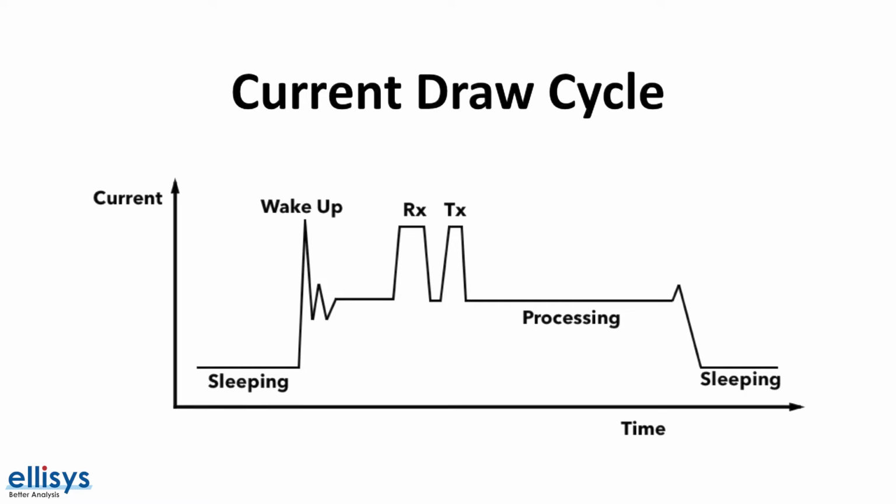Now, based on this cycle, we can notice a few variables that can have a great impact on battery life. At a high level, we could get the most optimization by not waking up as often as possible. Now, this could be achieved by adjusting the connection interval and the slave latency, which we'll talk about in a little bit. The next one is how much data we are receiving from and sending to the master. If you have control over the master device, then optimizing the amount of data being transferred can help a lot in reducing power consumption. The same goes for transmission from the slave device.